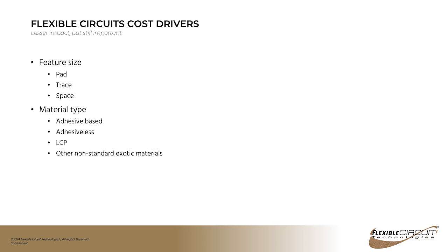Your material type can have an impact on the overall cost of the circuit. Adhesive based versus adhesiveless: the cost is not nearly as much as it used to be. It used to be a significant delta, but now those are pretty close, and so we use adhesiveless on a lot of parts, even though it's not probably as critical.